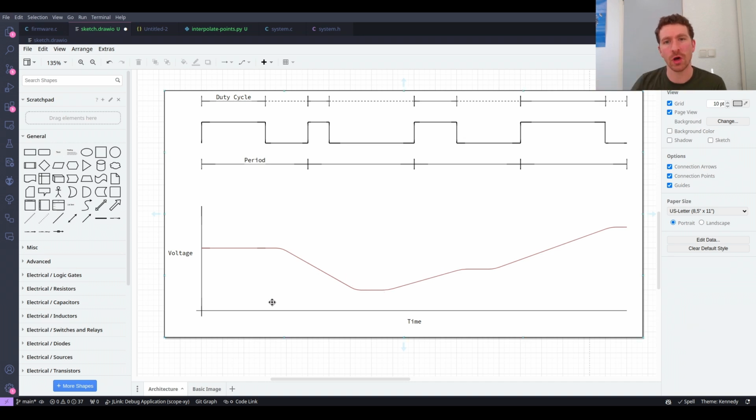Instead of being this sharp change, we take out those high frequencies and we slowly get down to that point, relatively slowly. And then when we go up to 40, we slowly creep up. We don't instantly end up at that level, but rather we pass through intermediate values, and then eventually as we go to 80. So this is how we actually convert our digital 1 or 0 essentially into this nice continuous analog signal.